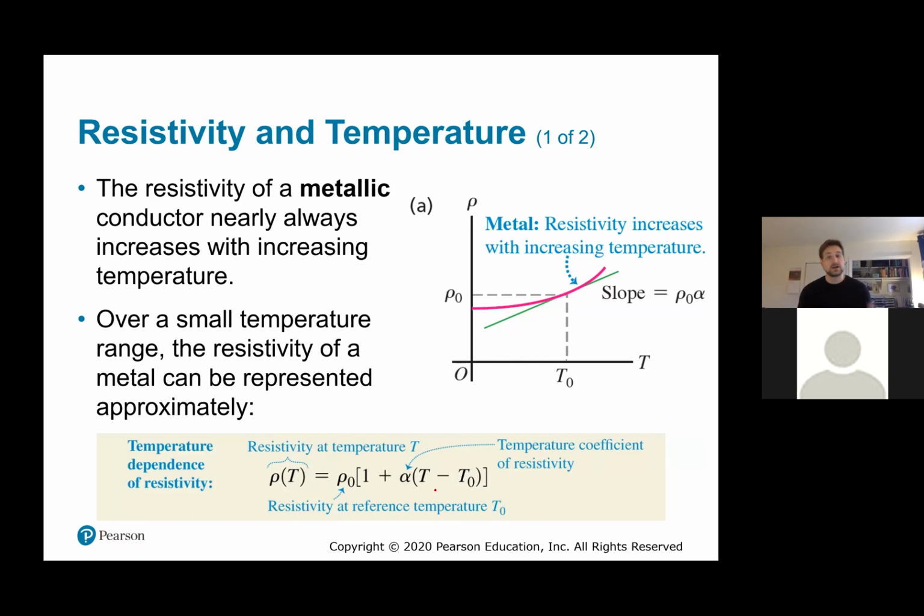The freer the electrons are, the more they can move through the metal. So we expect some temperature dependence. And yes, we can talk about the resistivity at temperature relative to some reference according to some temperature coefficient, the degree to which the resistivity changes with temperature.